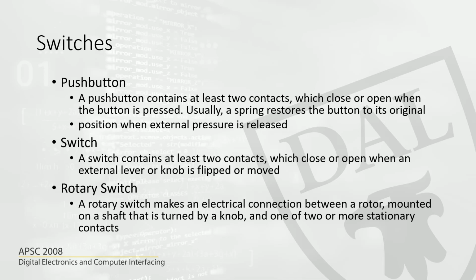But it can either be turned on without any external pressure or turned off without any external pressure. So you will have to check those before you buy a push button. The ones which we have in our kits are usually turned off when you don't apply any external pressure. That's the most common one which we have. But again, there are options available the other way around as well.